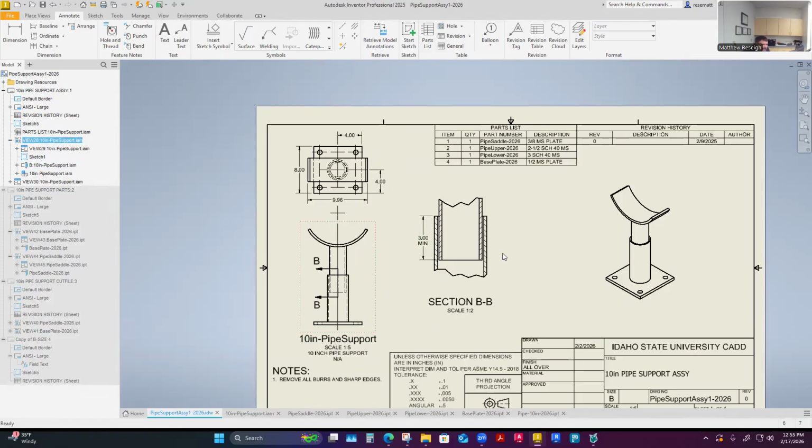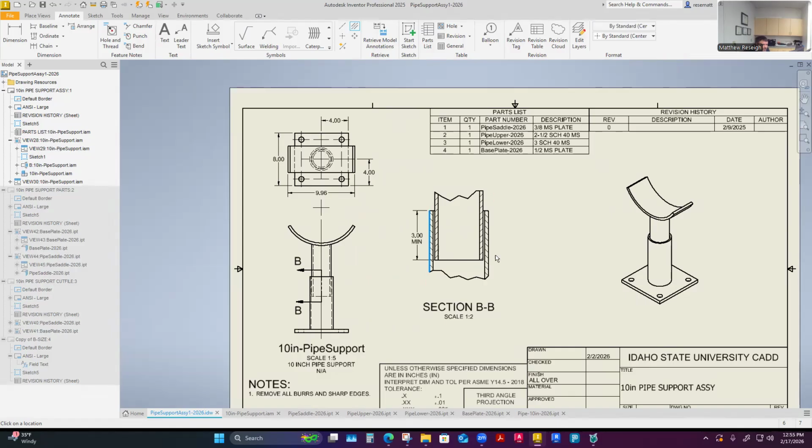So I was going to add that dimension, make sure you add center lines here. If I'm doing center lines between here and here, just pull these out. I'm just doing my center mark, center lines, pulling them all together. I like this to be shown together. I added a center mark here and then just pulled that through for the vertical center line. Since these are all cylindrical shaped parts here, I have a crosshair here as well, carrying my dimensions to where I've pulled my center lines.